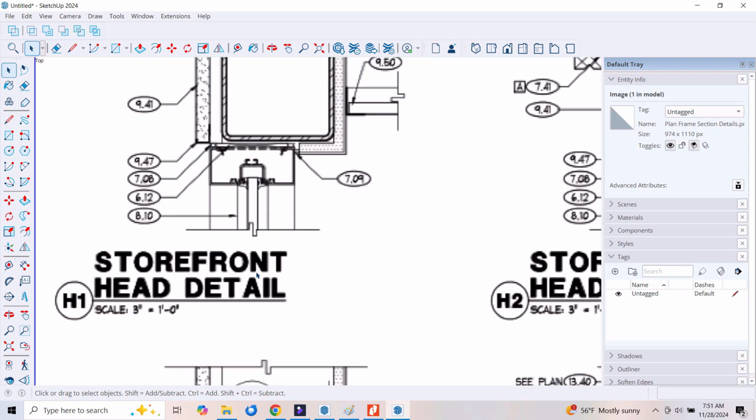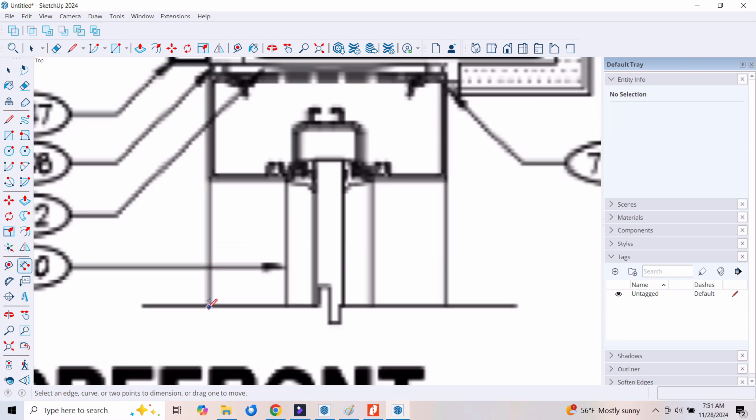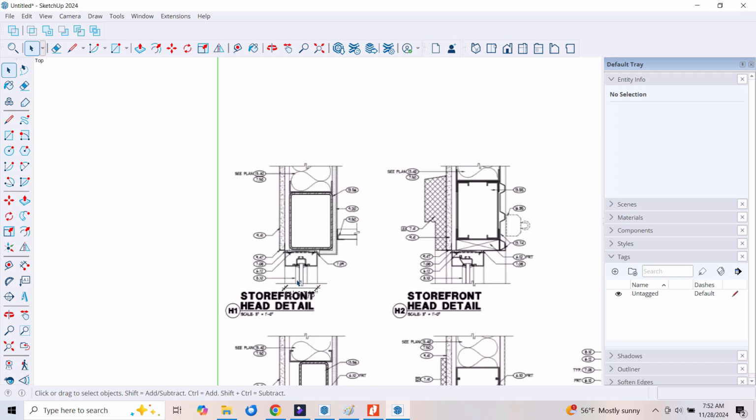And I think that, I'm just going to take a guess and say they probably drew this storefront frame 4.5 inches deep. So that shows as 11 foot 6 7/8. So what I'm going to do is punch in a calculator. 4.5 inches divided by parentheses 11 feet times 12 inches plus 6.875. That gives me a factor for scaling it.